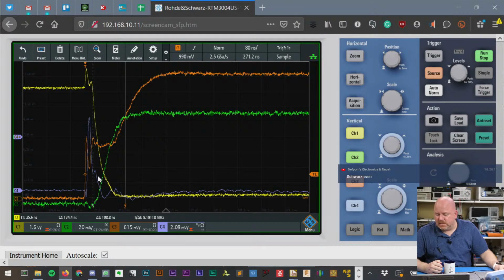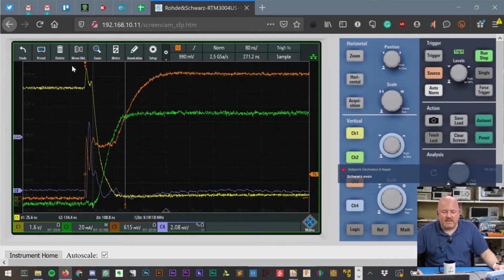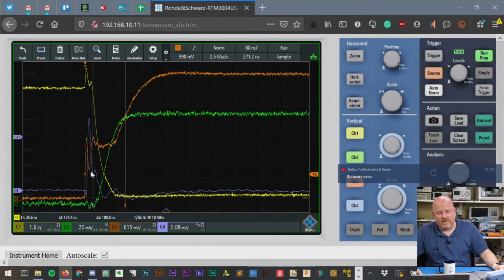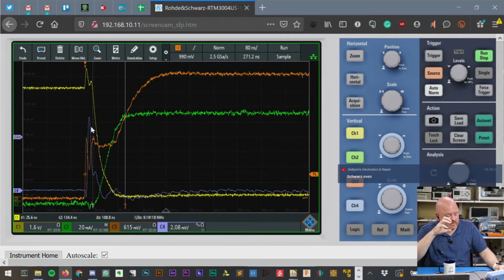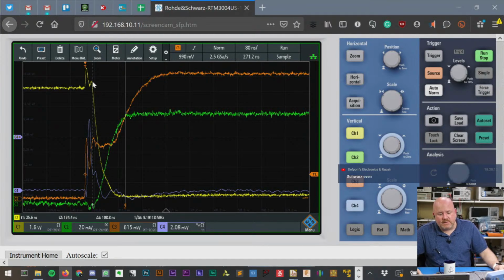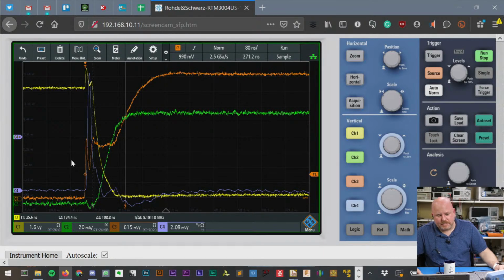So the spike, isn't it due to the parasitic inductive components? There's not really anything in the circuit that's highly inductive. There is an inductive spike from the inductive elements of the MOSFET, but I'm sure that plays into this, but it sort of doesn't matter. It's the total MOSFET itself. Because of the rate of how fast it's turning on, we get this spike.